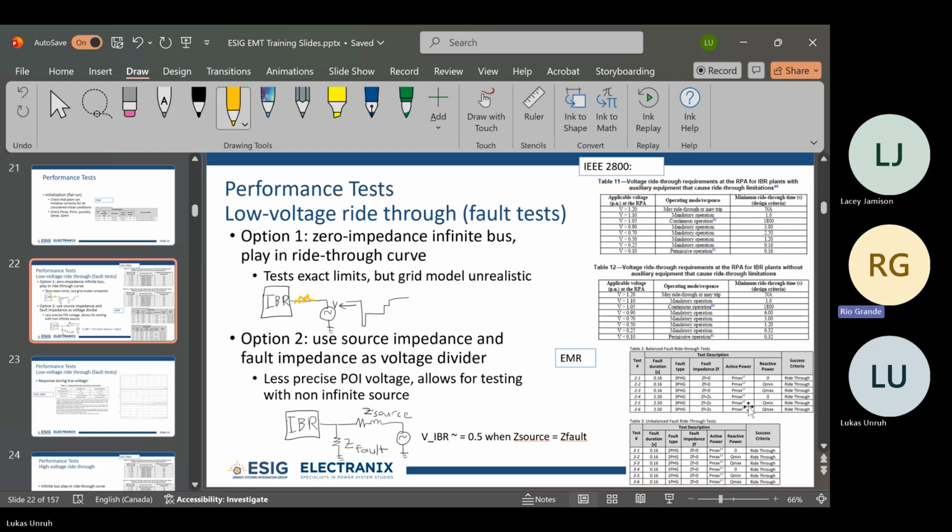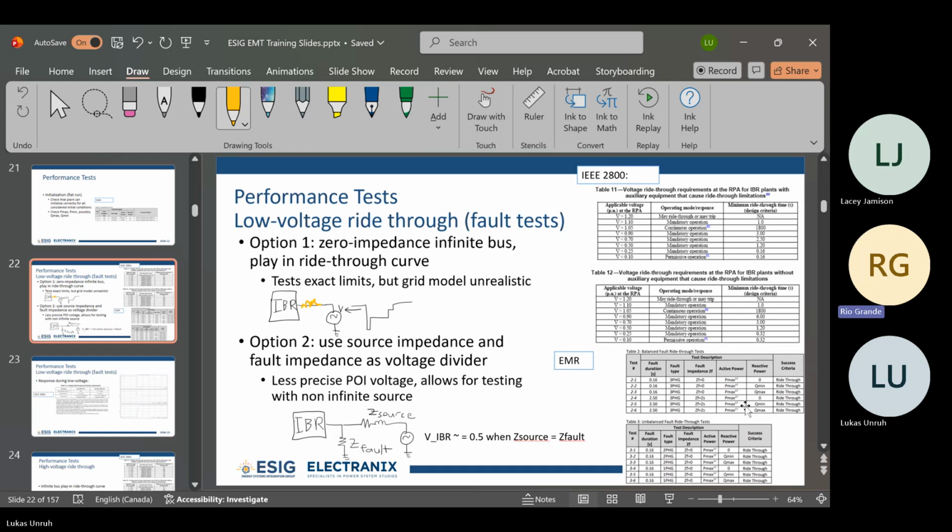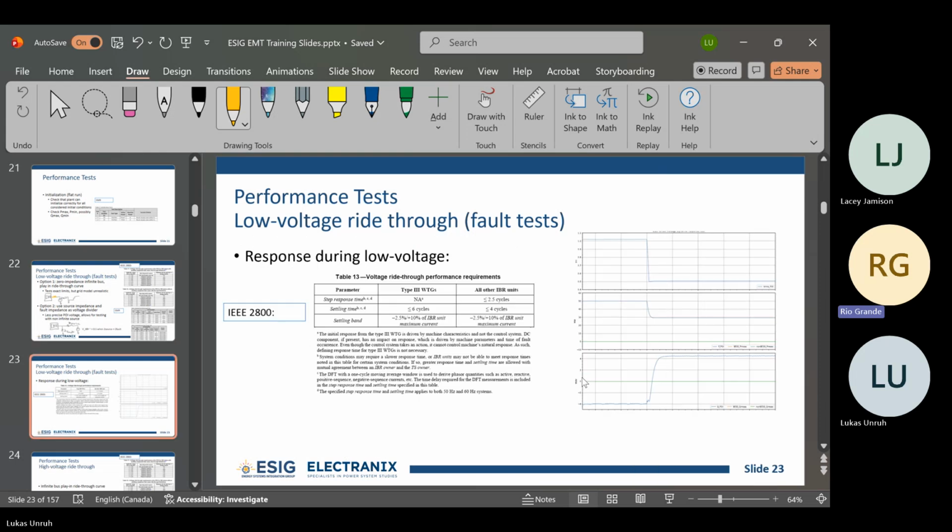Maybe full charging might be the worst scenario for the battery. So there might be a variety of different dispatches you look at for a hybrid plant or for a battery. Good point. The whole testing procedure's complexity goes up a fair bit when you're looking at multiple resources. Mostly the examples I'm showing here are for a single resource, but the principles still apply.